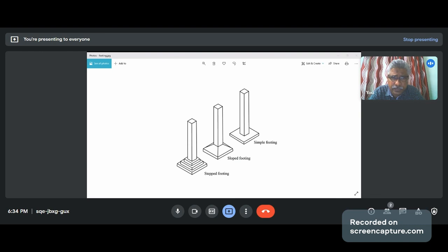And one more thing is that if you are given the column reinforcement, generally footing is designed separately, column is designed separately. But if you have the column design values like main reinforcement in the column, then you can check for the transfer of load from column to the footing pad. For that, some development length calculation, bond based calculation, etc., is there. That also we will discuss, so that we can be comfortable with the transfer of loading from the column to the footing base. Okay, so with that introduction, let us do a numerical problem.